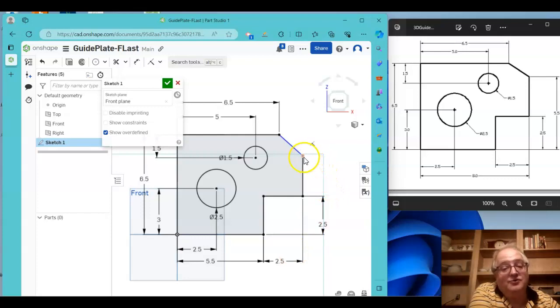And we drew this intersection point up here, which according to our drawing should be 5.5 inches. So we are going to double check to make sure that this location is correct. So let's go back to our dimension, and we're going to click from here to this intersection point right there.